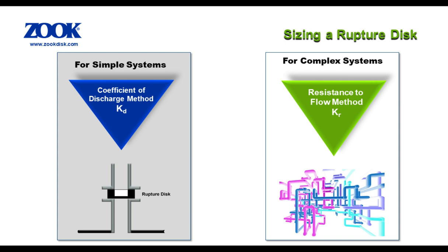Caution should be taken when selecting rupture disc designs based solely on low KR, as this can lead to a small diameter relief system with limited options to correct the situation if changes in the disc or pipework design are required in the future. Vendors can offer useful advice and sizing assistance, but ultimately, the responsibility of the sizing lies with the end user. The takeaway here is that right sizing is the goal, which requires collaboration between the user, process engineer, and disc manufacturer.